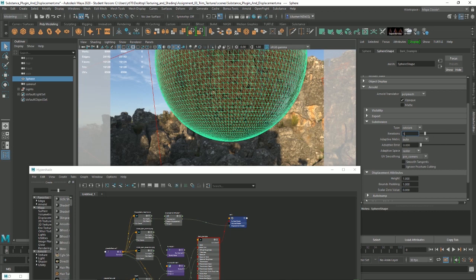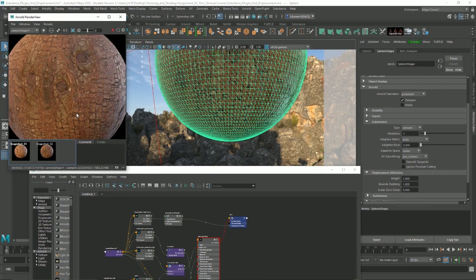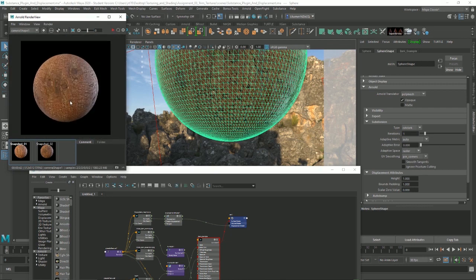And for a render's sake, this is only when you render, so it's really not too big of a deal. The convenient thing about changing it per object and doing it right here is it basically makes a reference of your object, so you're not messing with this mesh at all. When you go to render, it's going to reference this object and multiply the geometry by 4.